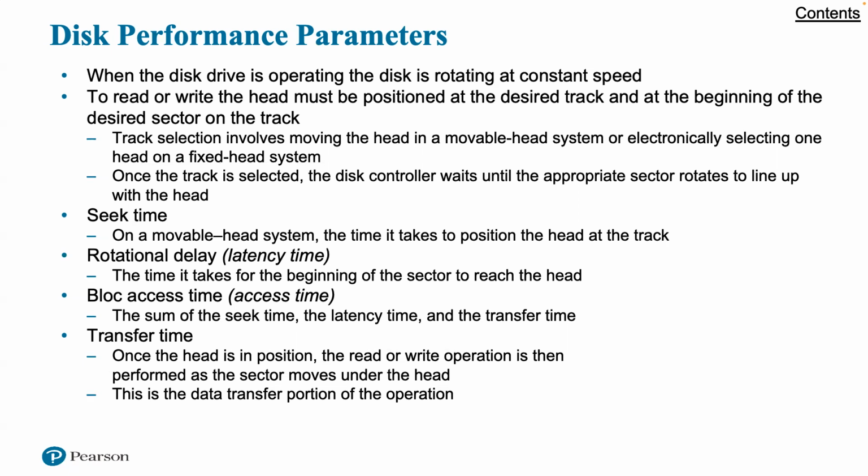Seek time is the time required to move the disk arm to the required track. It turns out that this is a difficult quantity to pin down. The seek time consists of two key components: the initial startup time and the time taken to traverse the tracks that have to be crossed once the access arm is up to speed. Unfortunately, the travel time is not a linear function of the number of tracks, but includes a settling time, the time after positioning the head over the target track until the track identification is confirmed. A mean time of TS is typically provided by the manufacturer.